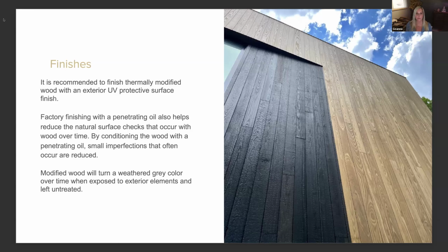Several different pigments, but keep in mind, it is the pigment that protects it from the UV. You will see manufacturers that specify softwoods that come oiled, or redwood, the red oak that'll come oiled. It's just oiled with a clear oil. The clear oil does not protect it from UV. So if you want to maintain the original color, that's where you have to put some type of pigment into the clear oil. A deck will have to be reapplied once a year.